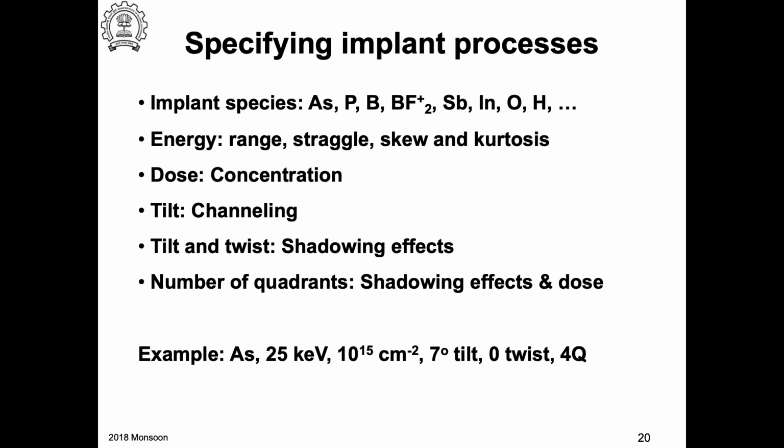Okay, I want to implant boron. So what is being said is to amorphize, by taking another material and implanting it at a higher energy. Implant some other species, not boron, and many times the other species can be silicon itself. The objective there is to just implant and create damage, to amorphize the initial couple of tens of nanometers.